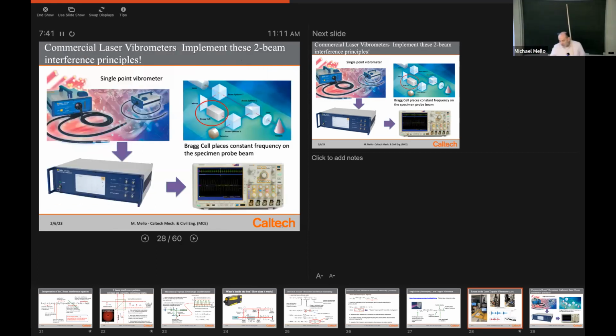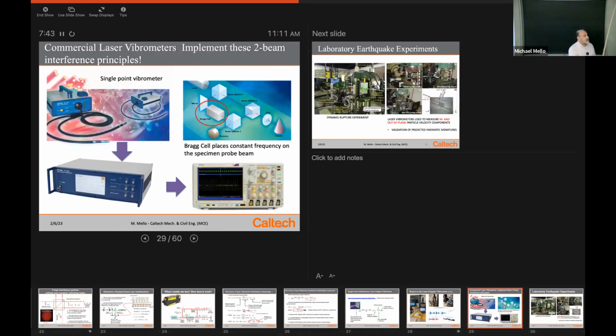Let me kind of give you a tour now. This is a device, this is a vibrometer, another one. It's just a faster one, and it has a fiber optic output. Very, very useful, okay, when you're trying to snake this light beam into a very difficult location that you want to probe. If you have some way of holding that probe in space, you can sneak it in, shine light off of that part of the structure, and pump it back into your device.